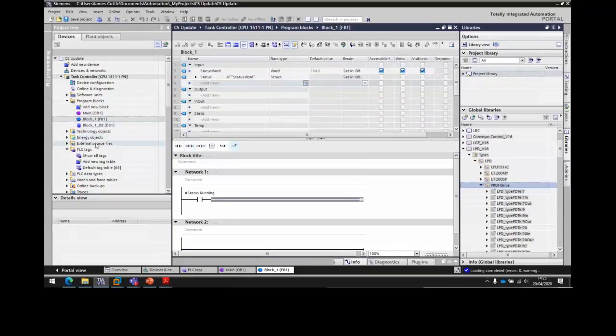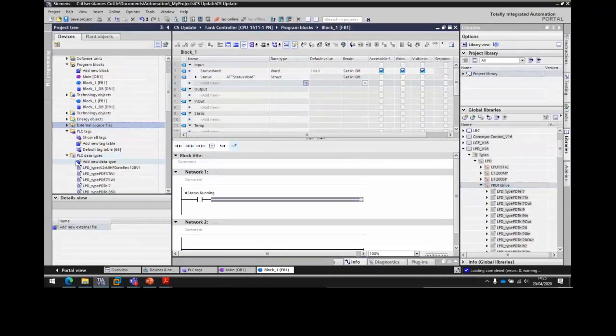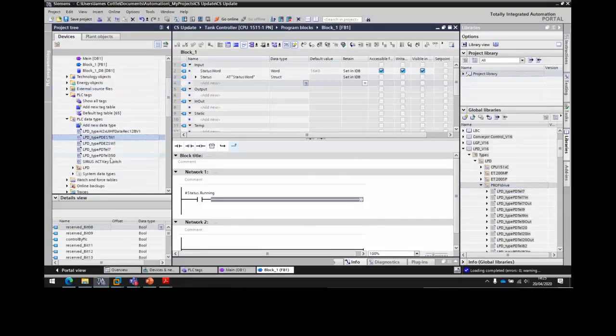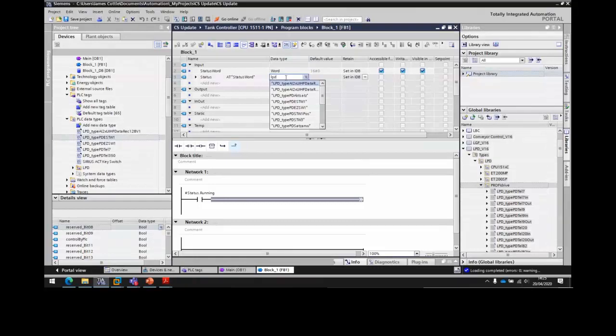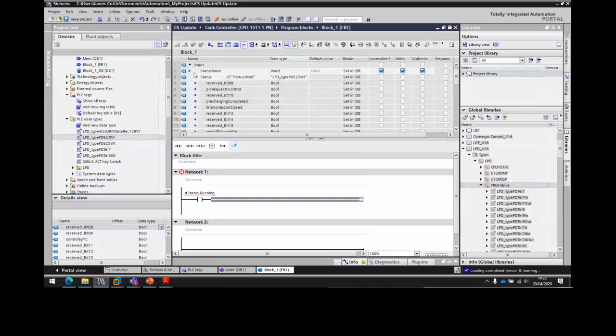I've actually copied some of these into my project here. So if we go look at PLC data types, you'll see I've copied in some data types from the library. So this means within my little block I was writing, if this actually was a drive status, then I can just simply say, give me the data type of status word 1. And now within my application code, I have the ProfiDrive Telegram status word 1 being fully overlaid on that status word, which is quite nice.